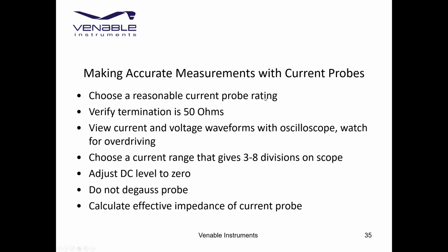Yeah, verify termination of 50 ohms. If you're using a terminator, people burn them up. You should make sure they haven't burned up the one you're using. Like I say, generally look at the voltage and current waveforms on the oscilloscope. You can see if you're having a problem.